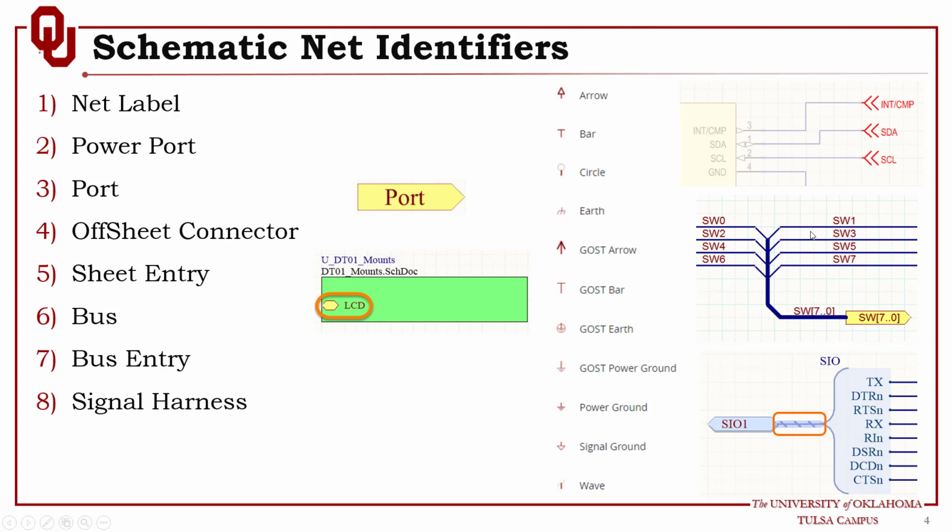This kind of identifier is used to create connectivity to other net labels with the same name on the same schematic sheet. The important point here is that they connect other wires with the same name on the same schematic sheet. These nets are automatically named by the net label text when you compile the project or the design.